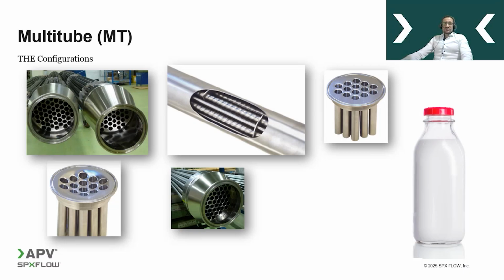In terms of the tube sheet design, we can actually provide two options. We can go for the flat tube sheet, which is ideal when there are no particles or fibers in the product. But also we can go for the conical tube sheet, which could be especially recommended for fibrous and particulate products, because it would improve the flow distribution.